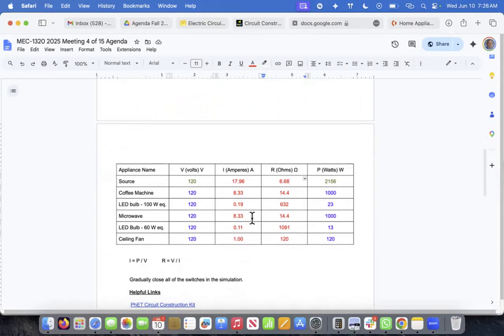So excuse me, the microwave and the coffee machine need to be on different circuits. This is part of load balancing. So you might have in your home or apartment one circuit that covers two bedrooms, but the kitchen, which is only one room, still needs to have multiple circuits. Otherwise, we're going to see an overload because of the appliances that are present.